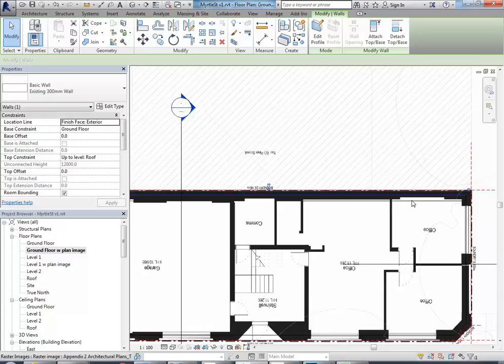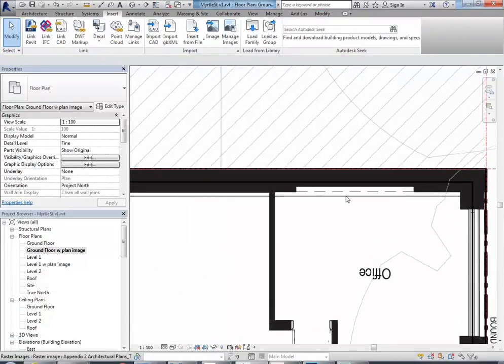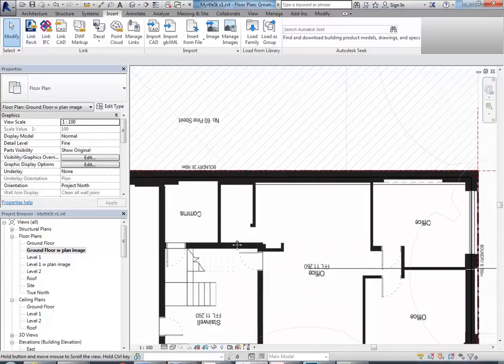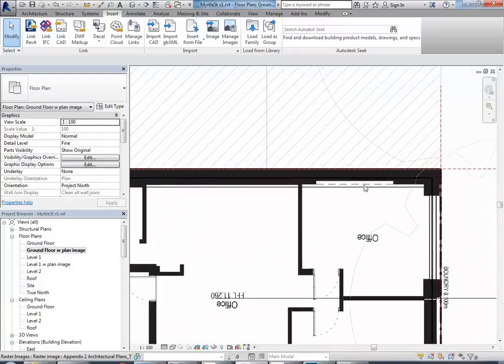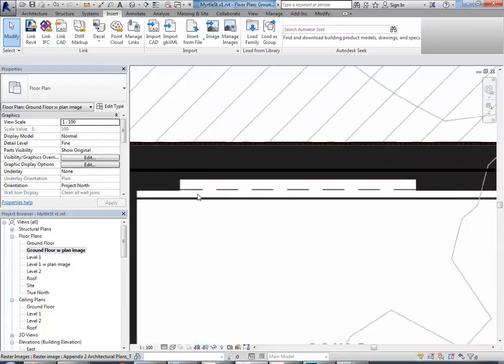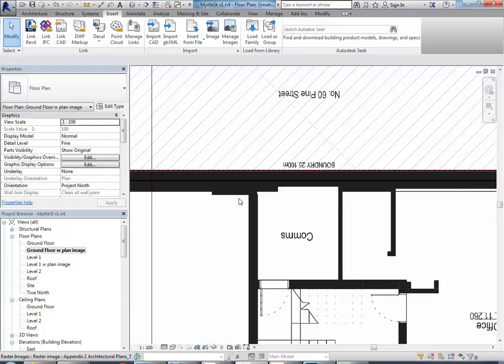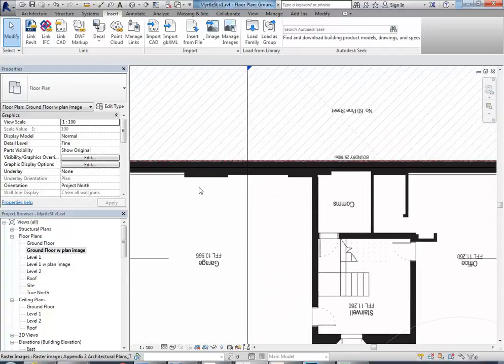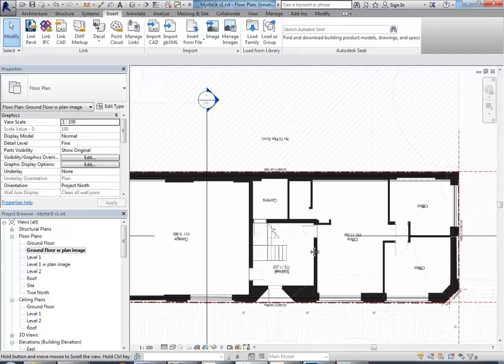And it's a nice thing to have, to pick up that detail that is there, the existing detail, especially for interior fit outs these days. It's a really important thing to be able to do. So what would that be then? Well, they'd be piers that would be, in most cases, supporting some of the upper level structure. Or, well, in this case, I'd say that's an alcove, so I'm going to ignore that one because it's got a dashed line there. So they've recessed there for some reason. And the rest of it, though, would be piers. You can see they mostly come out where there are other walls. And because they've added in some structural elements as well, they've got some extra piers for the beams that are in that garage and the other areas there.